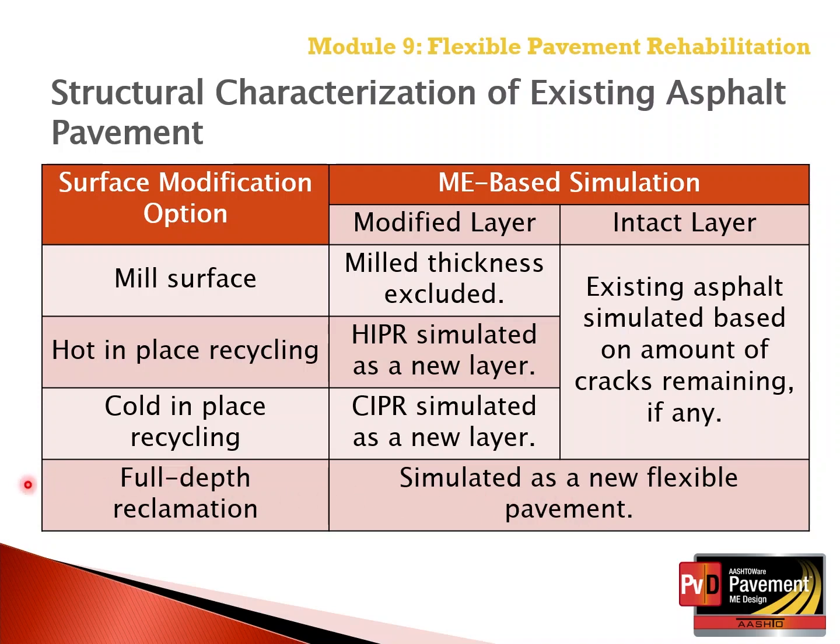The simulation is obviously dependent on the amount of additives that are included for the cold in place as well as the full depth reclamation. In addition, the existing asphalt is simulated based on the amount of bottom-up cracks that remain in the flexible pavement, if any, after the pre-overlay repairs and or surface modification option.